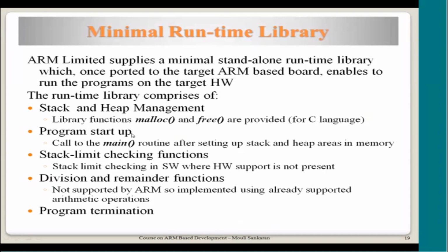And even to start a program, the entry to main, some startup code is given along with the library. And if the heap and stack space are interfering with each other, that limit is also verified by software functions. And then there are other additional functions also provided along with the library.